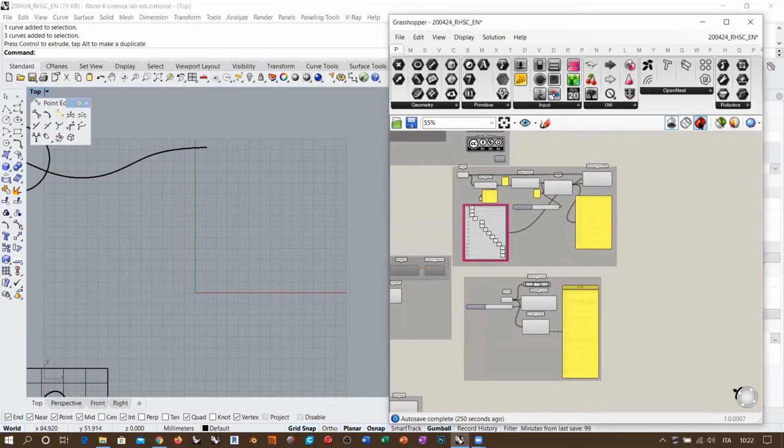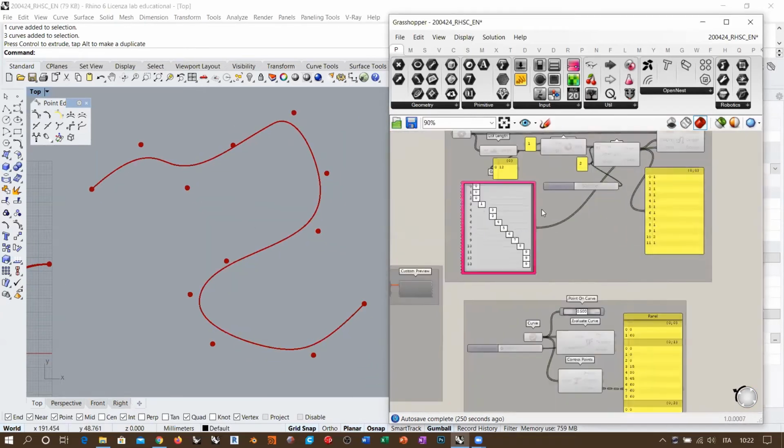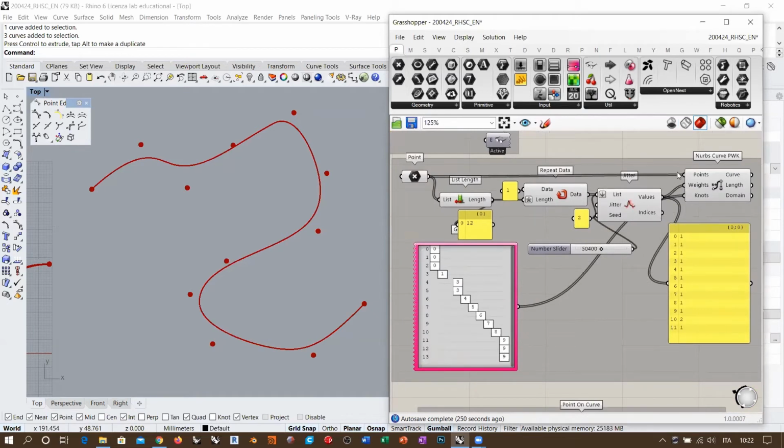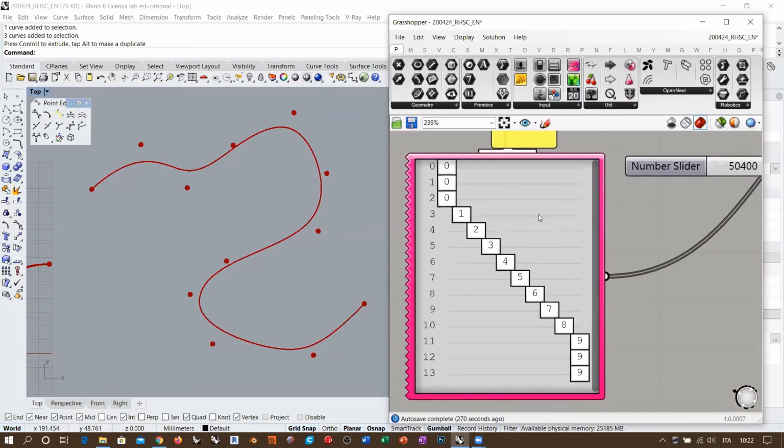Now, if you remember what we saw, where we were creating the generic NURBS curve starting from the knot vector, we saw that this is a uniform vector, right? But we saw that we can create a full multiplicity knot along the path. Full multiplicity knot for a degree 3 curve means 3 equal values inside the knot vector, in the inner part. Having a full multiplicity knot in the first and last part means that the curve starts from the start point and ends in the end point.